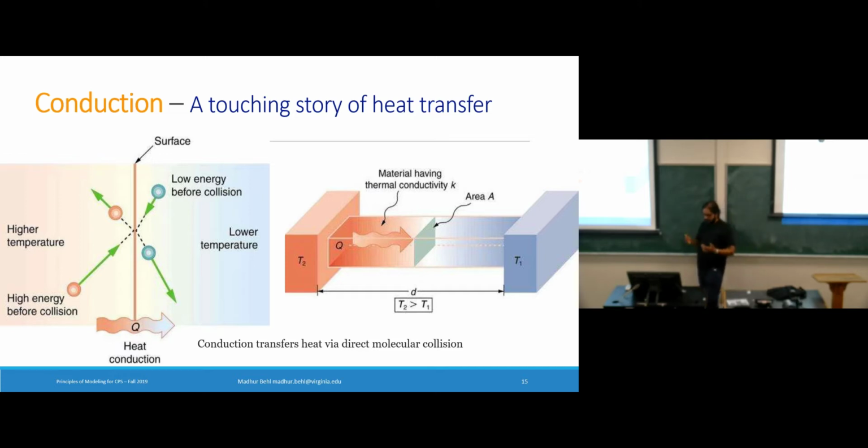In fact, you may not think about temperature in this way, but temperature is nothing but our estimate of the average kinetic energy of molecules in a body. Okay? So temperature is actually velocity in some sense, of how fast things are moving about. So when things are agitated at high temperatures, there are a lot of collisions with the neighbors who are not yet agitated. And so on average, everybody wants to be equally agitated. There's this mismatch of vibrations of molecules. That's where conduction stems from.